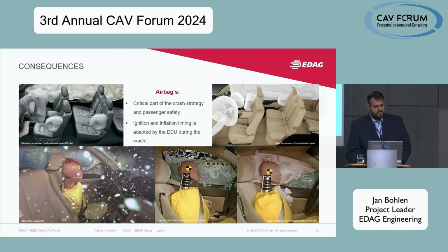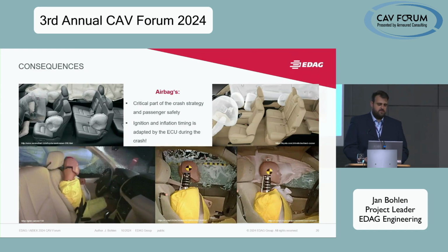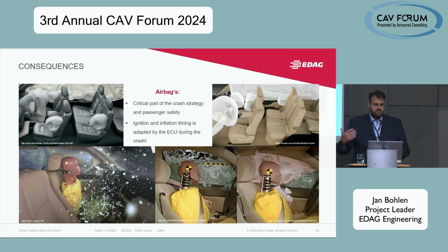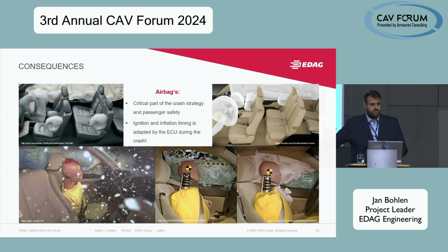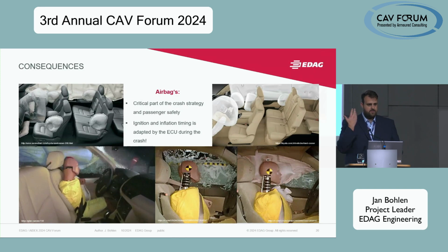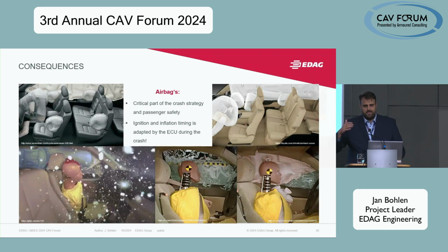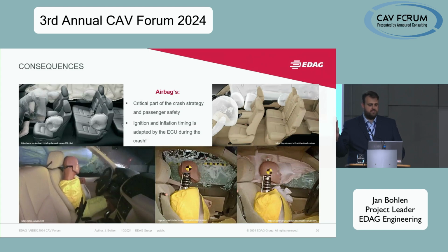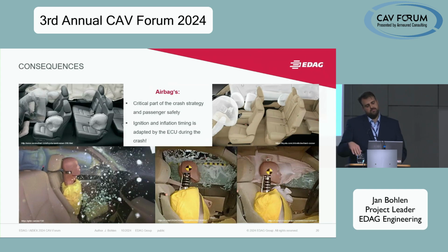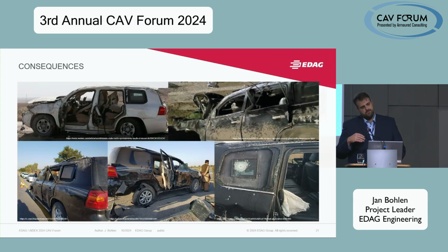Especially the curtain airbag is the airbag I'd like to talk about, since when we are speaking about a side crash scenario, this is what really counts, the side airbag and the curtain airbag, since it has the ability to prevent the contact of the head with the rigid structure or the safety glass on the side, and also minimizes the bending of the head regarding any neck injuries.